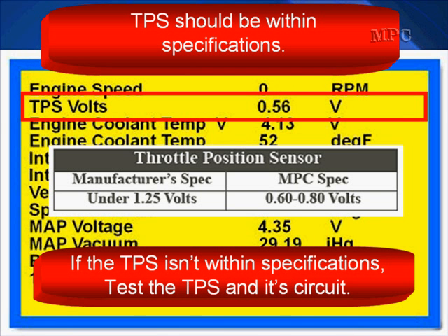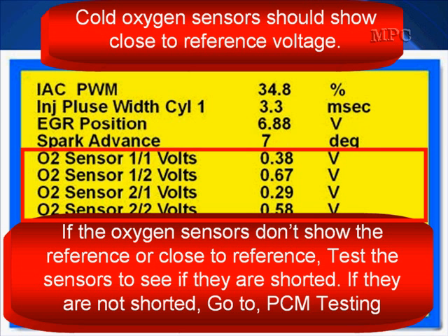TPS should be within specs. If the TPS isn't within specs, test the TPS and its circuit. You can see where we're going here. We're just going to go down through the data bit looking for wrong data.